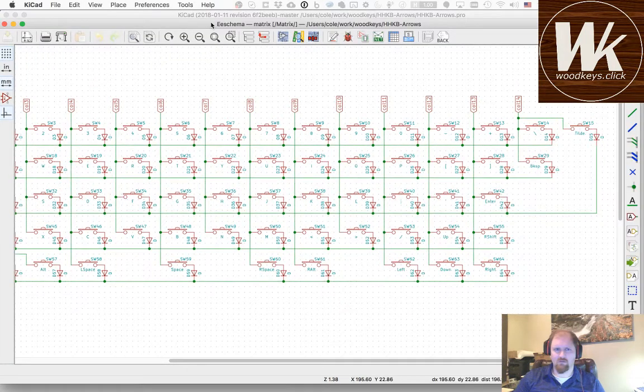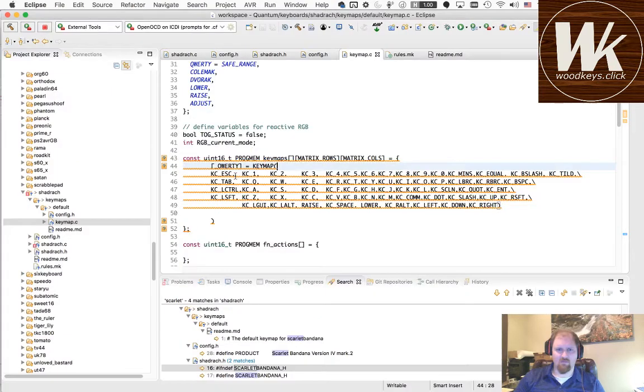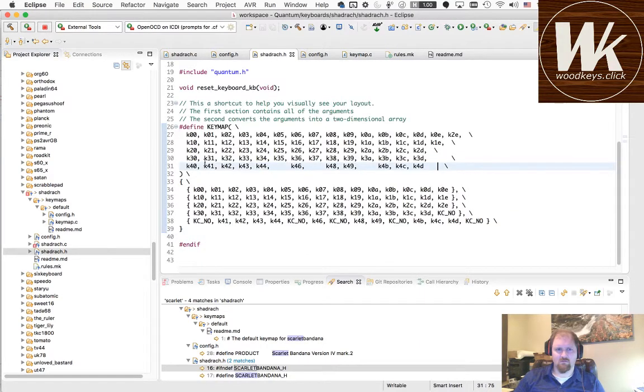Looks like that. This is what we worked on in the very first week. So I should have 64 switches. That's what I'm showing here. So my key map is correct, and the problem is in my key definition here. The question is, what's defined over there that's not defined over here? Oh, it's because they all start with 0. I've got too many. Oh, just one too many columns. See, that's easy. Easy enough.